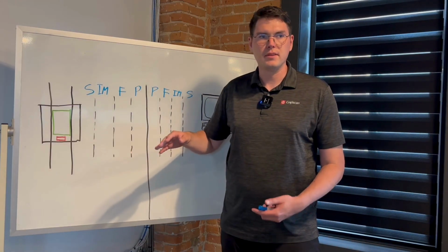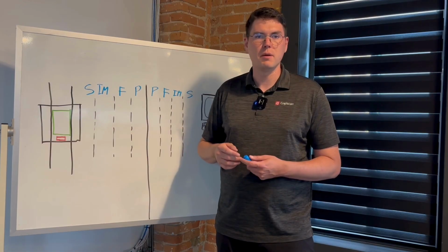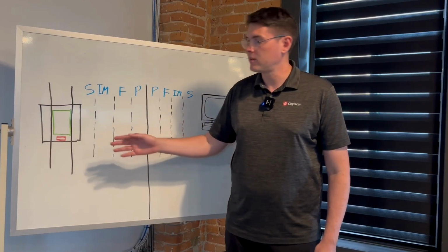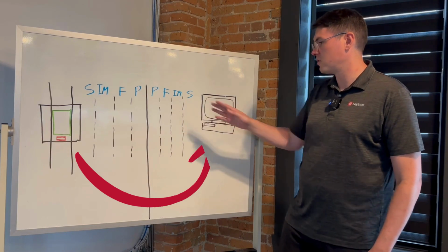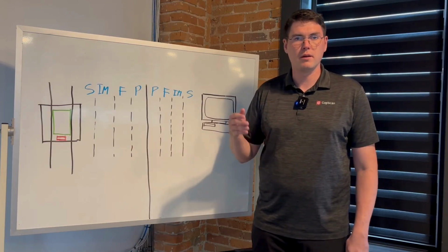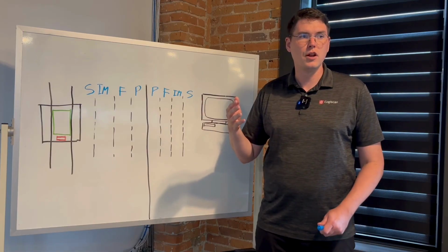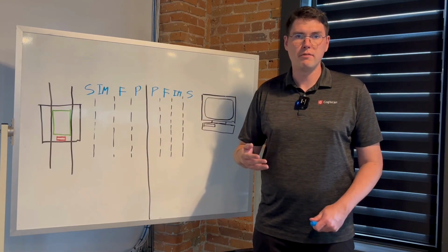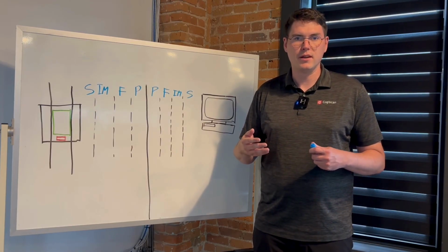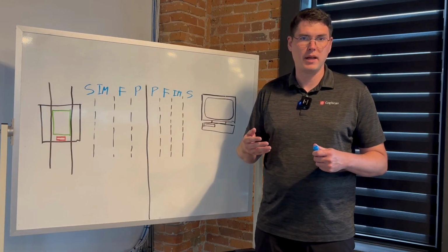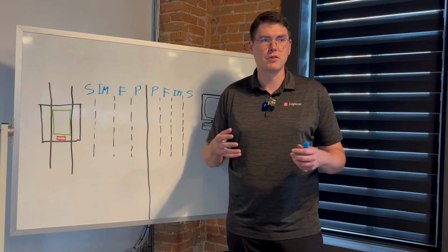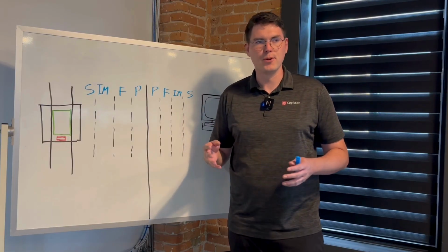So this is where it's very different in the PCBA assembly than it is in other industries, because in the PCBA industry, we don't have a direct connection of the data from the barcode reader to the MES. And there's very good reasons for it. PCBAs output a lot of data. Every placement on the machine could be a data point. Every nozzle for every head has process data, multiple process data for everything. It's just a lot of continuous data. It will completely explode the bandwidth of your shop.